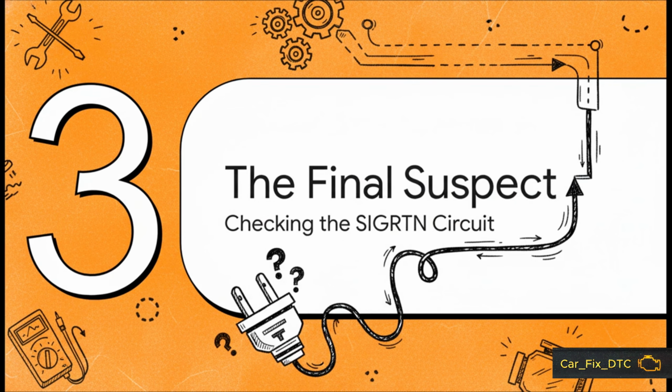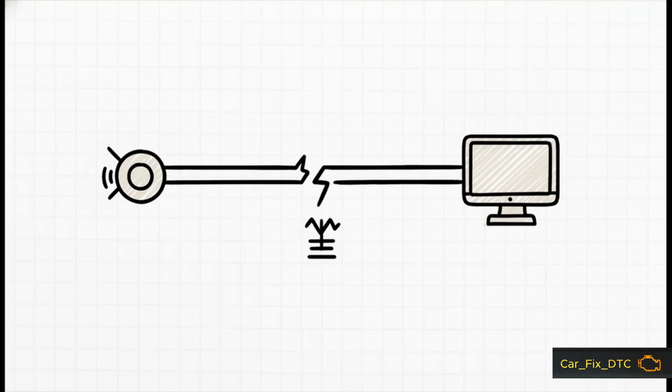Okay, so what if you've checked that entire FRP circuit and you found no opens and no shorts? Is our investigation over? No, not yet. Now we have to turn to our final suspect, an issue with something called the SIG-RTN circuit. Our last potential culprit is an open in the SIG-RTN, or signal return circuit. This is basically the ground wire for the sensor. It's the return path. So if this return path is broken, remember our racetrack analogy, the signal has nowhere to go. And that can also cause that intermittent or erratic reading that triggered the code in the first place.